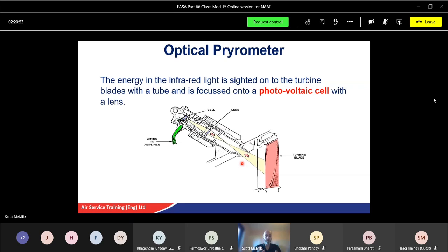And then once we cleaned it, it was okay, we put it back in there. The newer ones now have a little, what's called a shroud, that extends slightly further. What that helps do is induce, because you've got the fast moving gas flowing over it, it pulls all the high pressure from inside the pyrometer itself. So that stops the carbon building up. Occasionally they do carbon up, and you have to clean them.